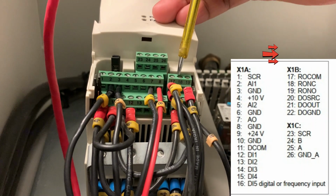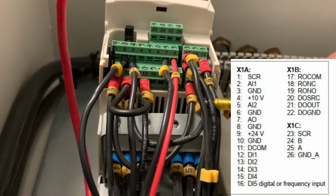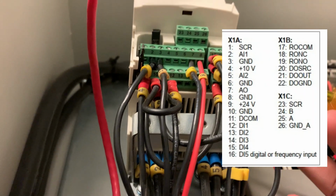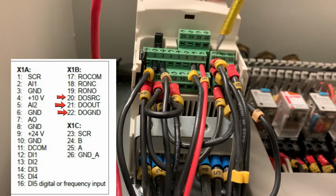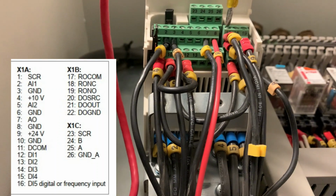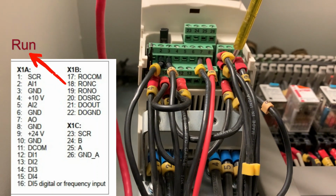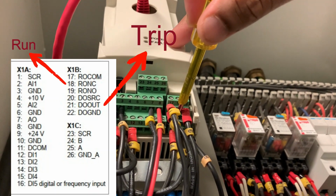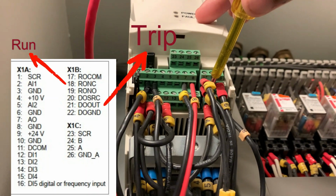One relay, and behind this there are 3 terminals that we can use as either relay or frequency output. The terminal numbers are 20, 21 and 22. This relay I used for run status. When our VFD runs and the motor runs, the relay gets actuated, and when the VFD is tripped, there is one more transistor output relay on this side that gets actuated, and I will get the alarm in the BMS that the motor has tripped.